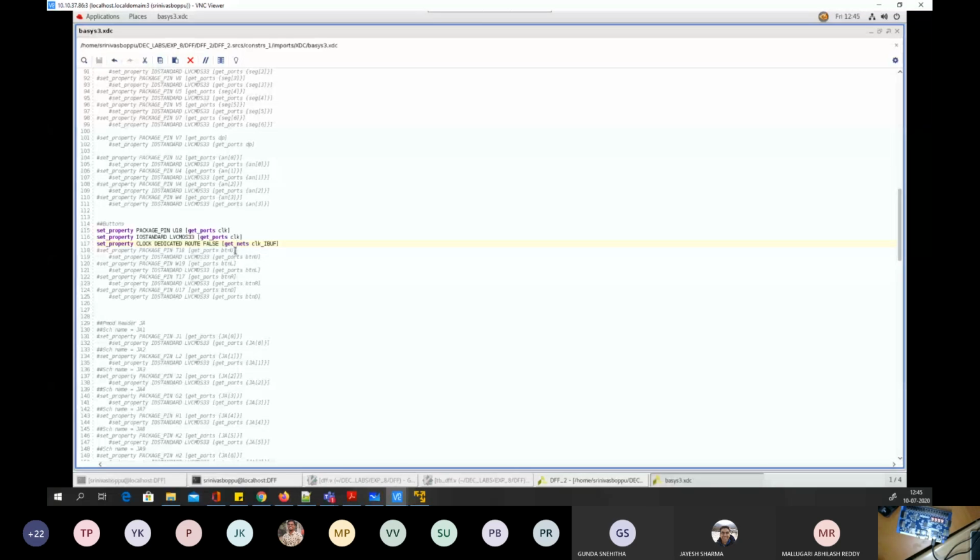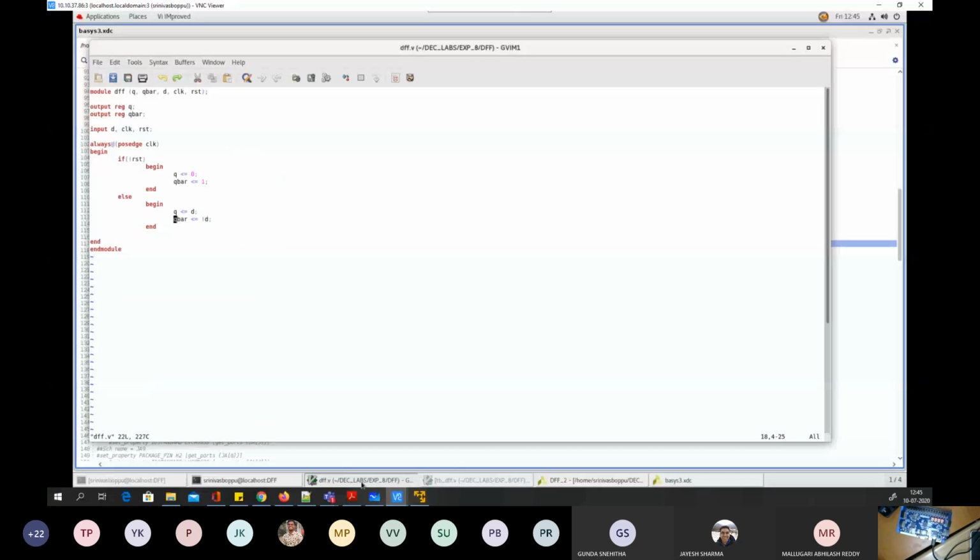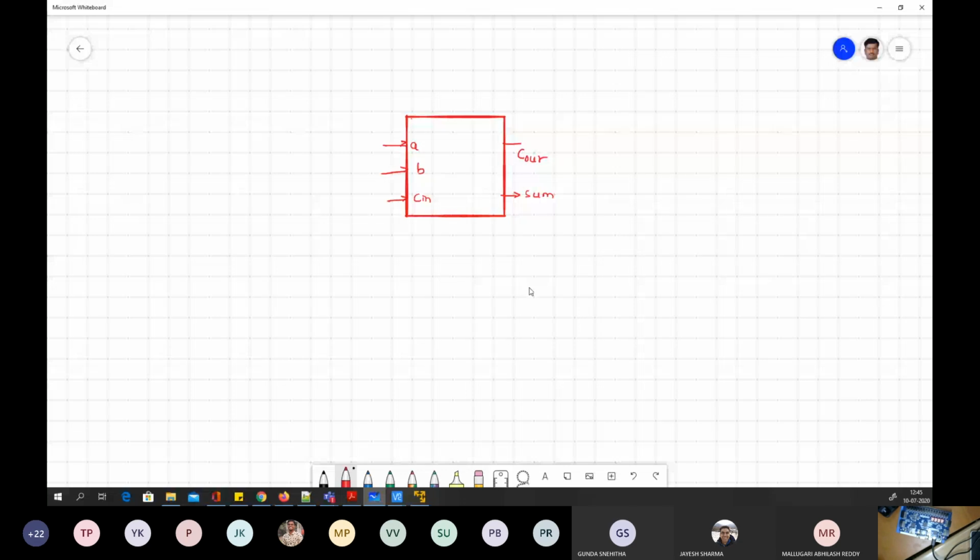Okay. So here, what we are trying to do is, maybe again I can have a look at this code. What Vivado does is that whenever you have something mentioned in this sensitivity list, it thinks this is a clock, of course, in a normal design. So maybe this is your clock. Clock is a kind of a versatile signal or a global signal.